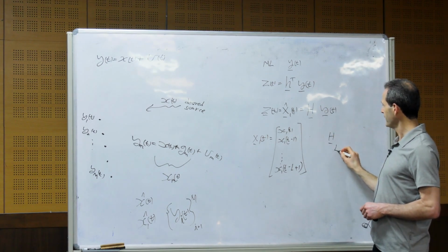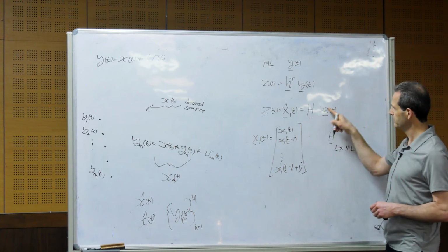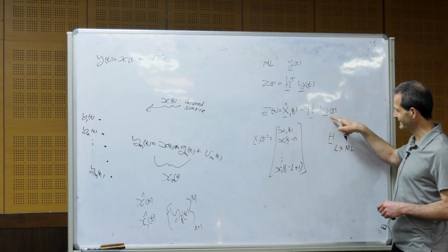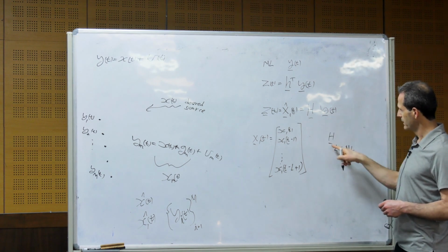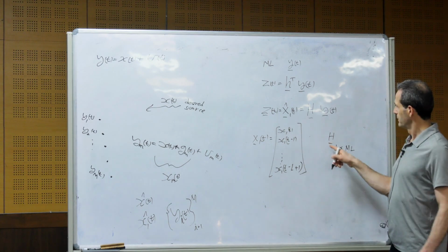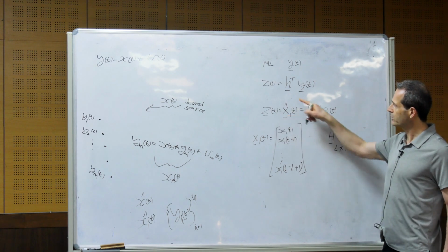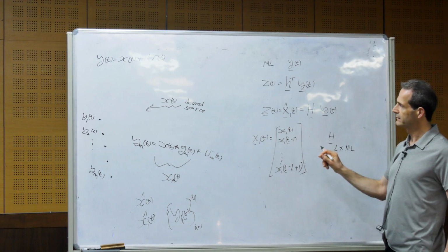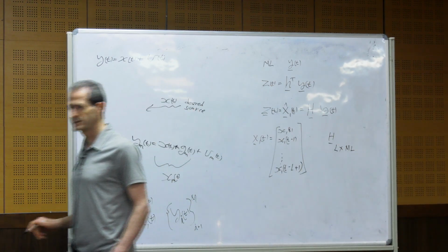It will be L by ML. The length of Y is ML samples, because it contains L samples from M sensors, and H is an optimal filter of size L by ML. Then we get a block of L samples that we estimate, related to the samples of the reference sensor.